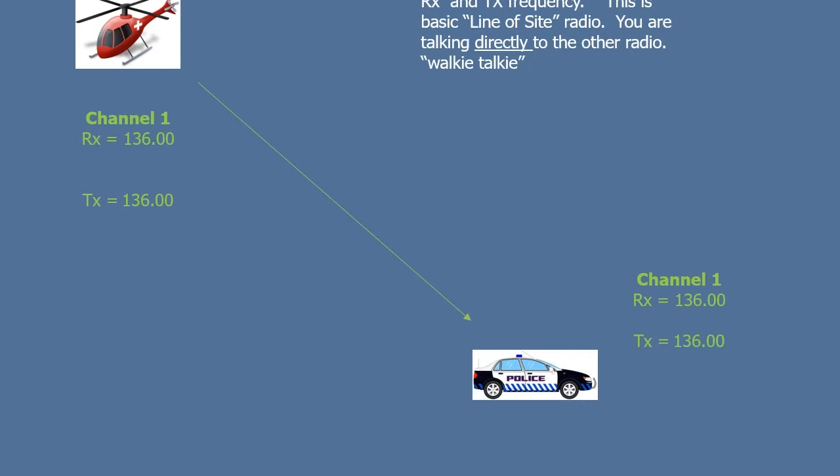It is walkie-talkie style radio in its easiest form. My radio is talking directly to your radio. There's nothing in between. We're not talking through anybody or towards anybody. We are just talking radio to radio. In a helicopter, we have a greater line of sight than we do on the ground. Again, these cars and these portables that are on the ground, they may only reach 20 miles and they're only meant to go as far as the first repeater. They are not long distance radios. Our helicopter gives us a little bit better performance on that because we have altitude on our side, and I have seen the radios work up to 40 miles line of sight.